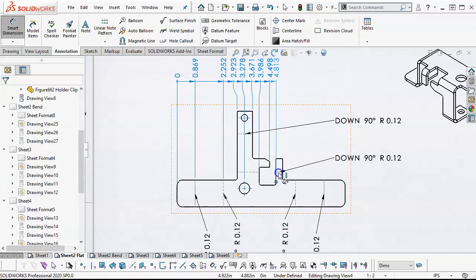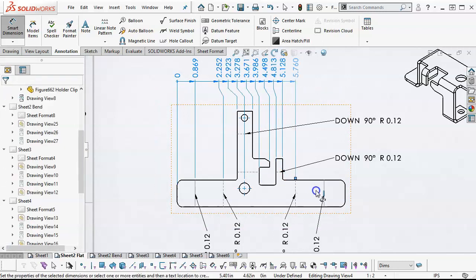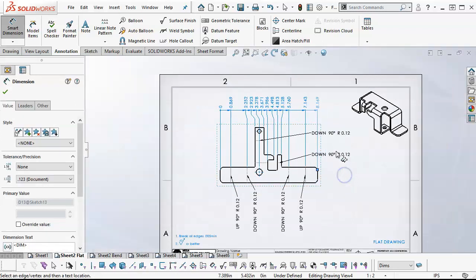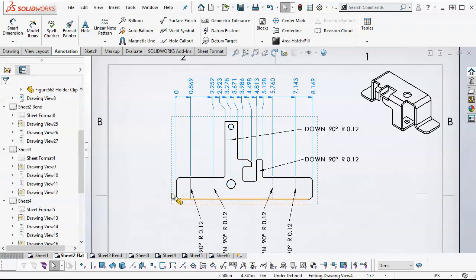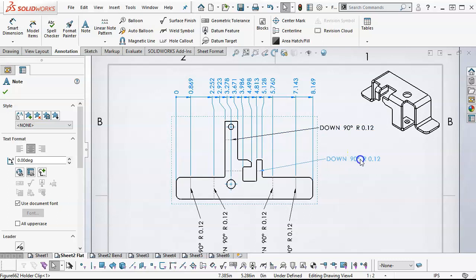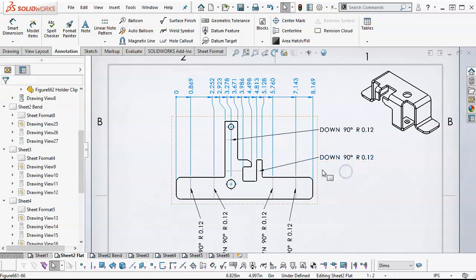It's going to get kind of busy if we go across all of these, but we'll see what we get and clean it up as we go. Alright, so again, because of the K values stretch, if we were to just add those numbers up, but every time we include a bend and we figure out those internal stresses that are going to stretch or shrink the material, we're going to see some variation in those lengths. So as we refine and actually go through the bending process and get results, these numbers may need to shift a little bit. We may have to go back and adjust our K values to get something more realistic.